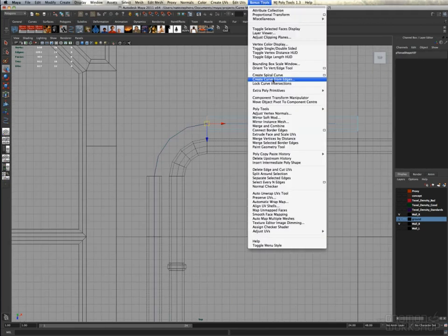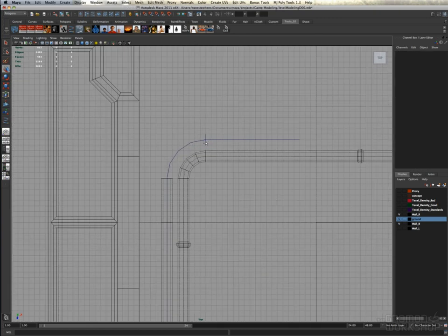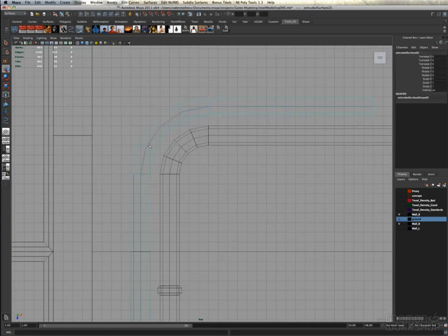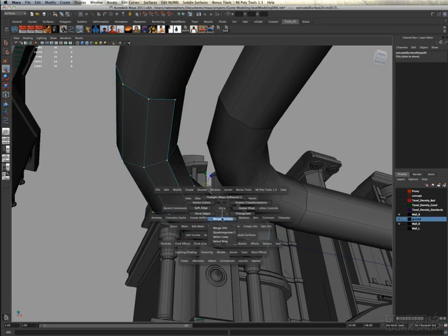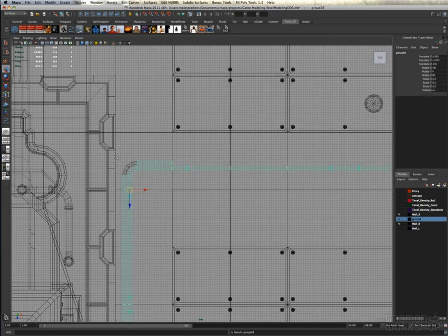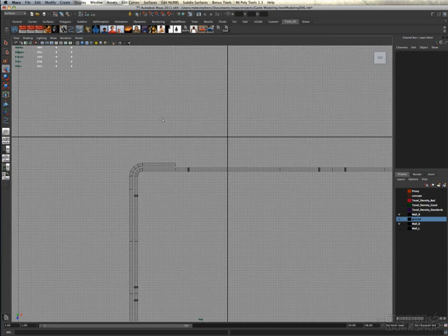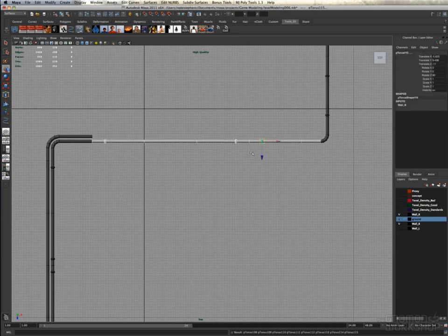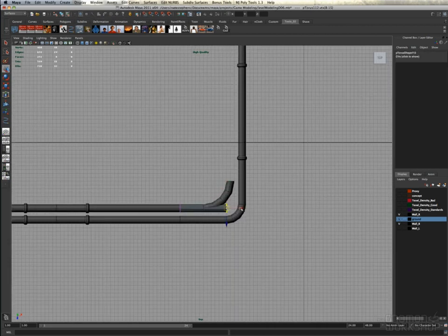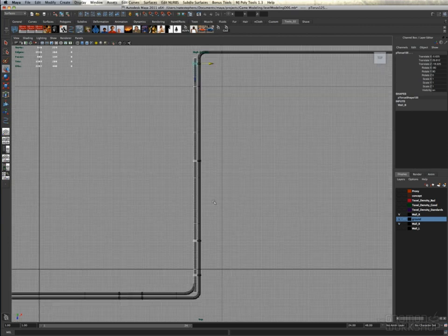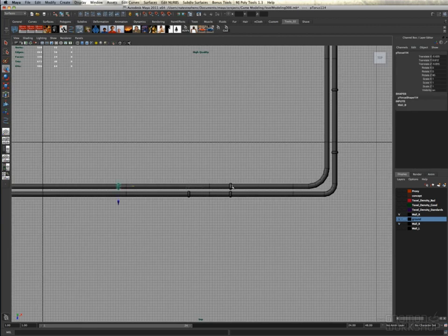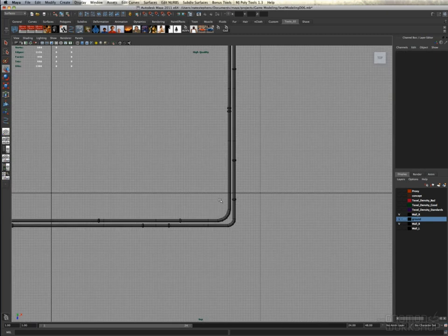So since I decided to put two curves next to each other, just scaling up the 90-degree bend piece of the curve is not really going to work. So you'll see what I just did there was I redrew a curve and used the lattice tool so that I could space it out evenly, and these two curves will fit snug next to each other. And now what I've done really is create a new curve library piece that will work in this kind of situation where I have two curves next to each other.